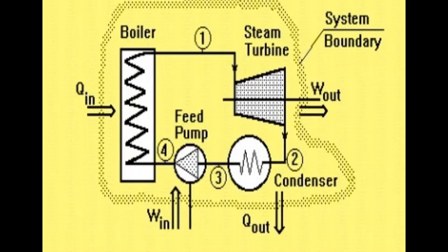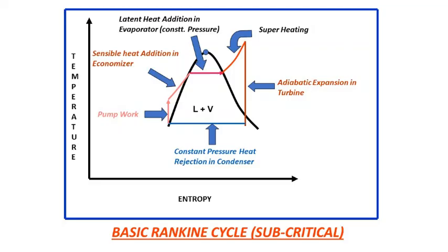If we put this practical cycle in the Rankine vapor power cycle, applicable for subcritical regime of operation without regenerative feed water heating, then we find that there is a feed pump, boiler feed water feeding pump, and that pump is doing some work on the water to take it to the boiler.